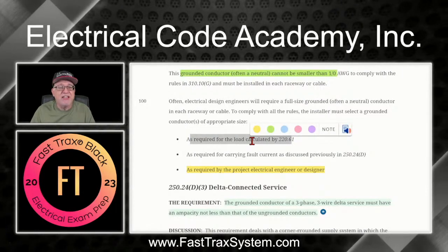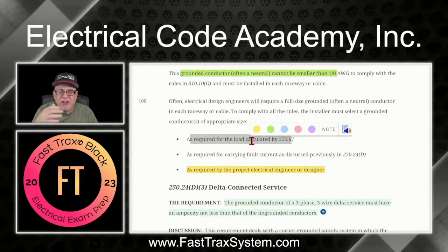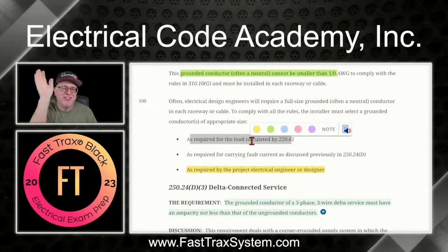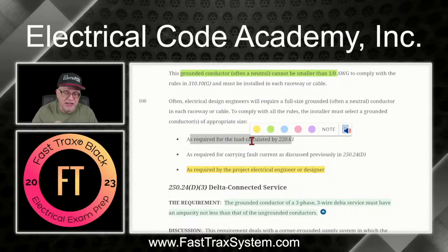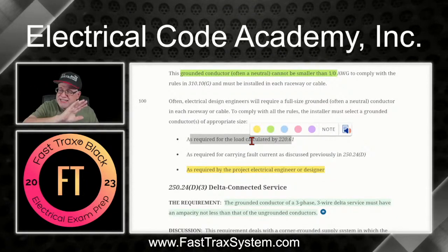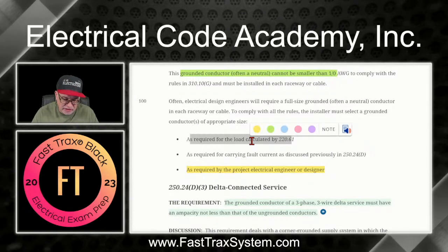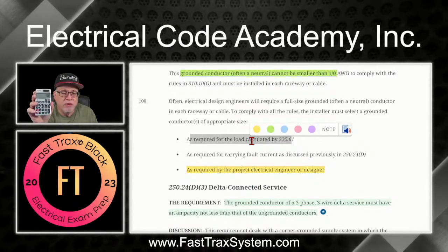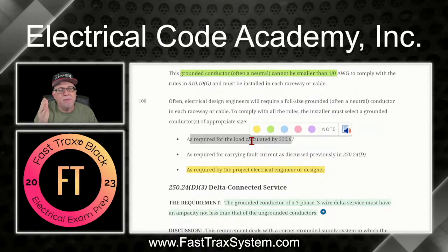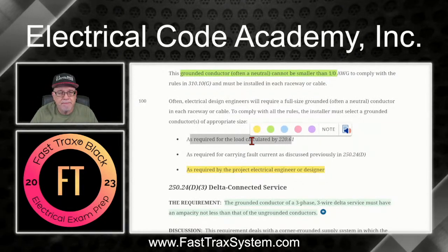If my calculation, for example, was that I had 600 amps of neutral current, I'm just throwing a number, and I take that 600 and divide it by 3, then I have 200 amps. So I have to have a 200 amp conductor in each one of the raceways, okay?